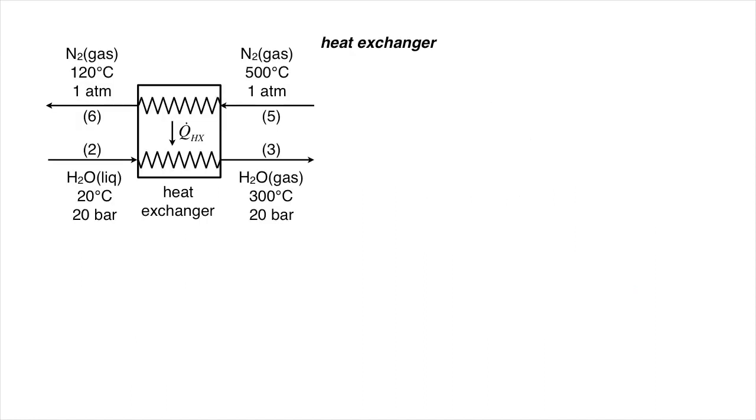Okay, so now let's look at the heat exchanger. The issue we need to address here is how much hot nitrogen gas we need to heat and boil the H2O under the conditions outlined in the process. For convenience, let's place the control volume around the whole unit, in which case we don't need to think about the heat passed from the hot side to the cold side. We can just treat it as an adiabatic unit with streams entering and exiting.